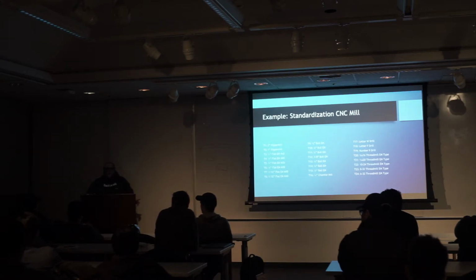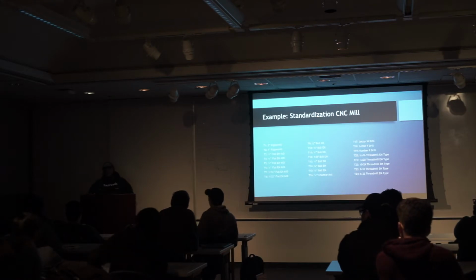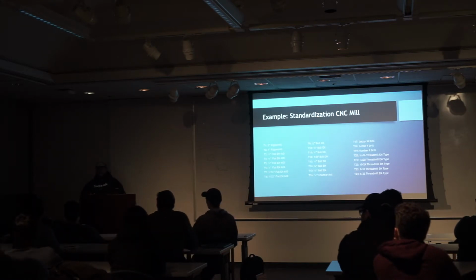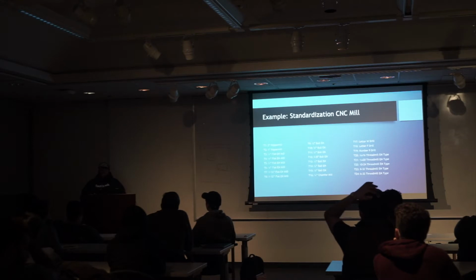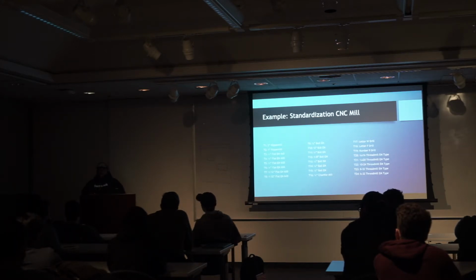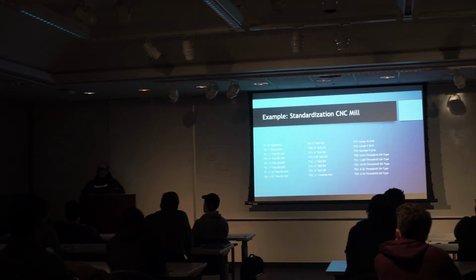Okay, so we have Lang 0-point clamping systems, which pretty much use pull studs at the bottom of all of our vises. So they automatically locate the plates we have on our table. On our big CNC we have 4 different zeros, and depending on what plate you're working on, that's the zero to use. It's just in the center of the plate that you put the vise on. And we have all of our vises in CAD, so everything is compensated. We can start programming the part.